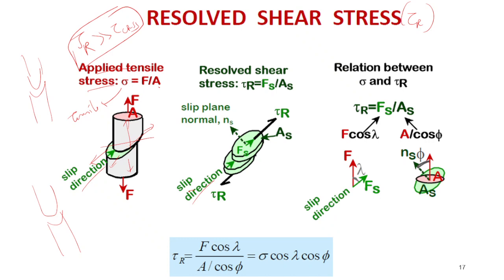Yeah, so that is the thing. So I will check whether it is different for polycrystal and single crystal, and that too for metal, because in metal you will have this cup and cone formation, whereas if it is some brittle material, say composite or ceramics, usually it will be somewhat, I think, in this particular 45-degree break, a sudden fracture instead of cup and cone formation.